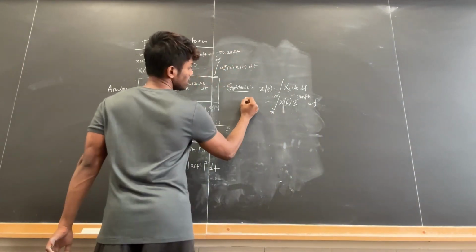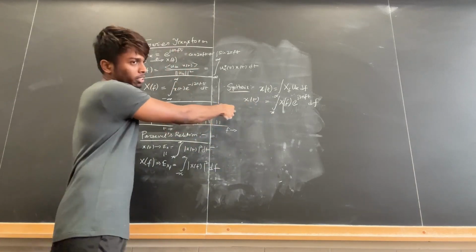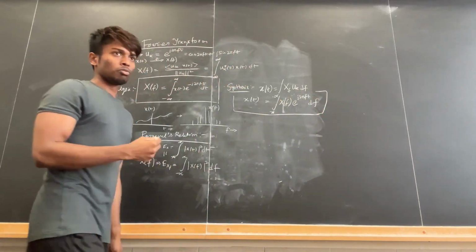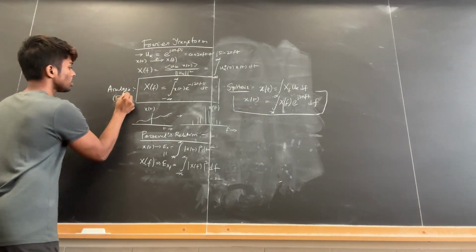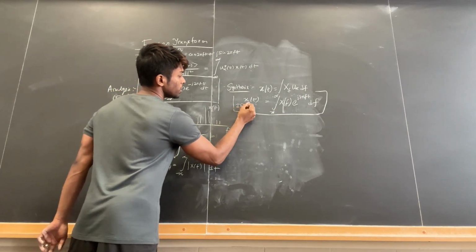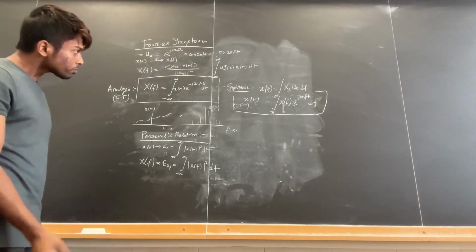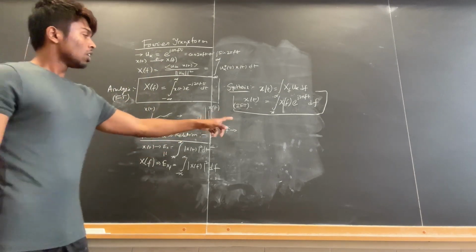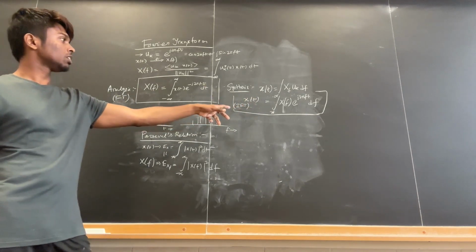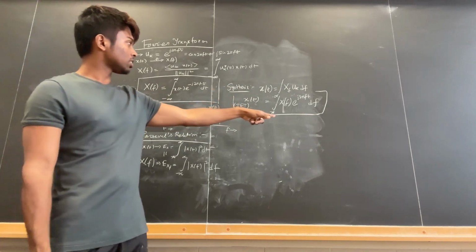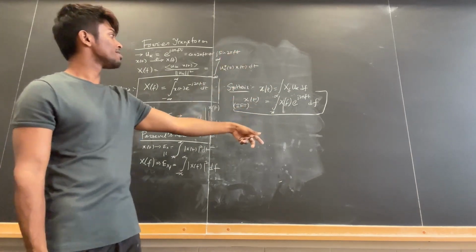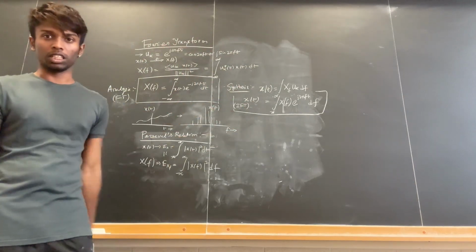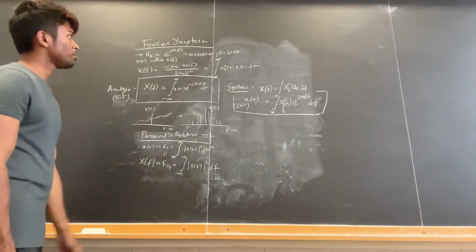So this particular integration gives us an approximation of the signal back. This is our synthesis formula, which is called the inverse Fourier transform. If this is the Fourier transform, then this is the inverse Fourier transform in the continuous time domain. That means we basically take a weighted linear combination of the Fourier basis, weighted by X(f), which is the Fourier coefficient, and that is the signal x(t). That's the idea, the statement behind the synthesis.